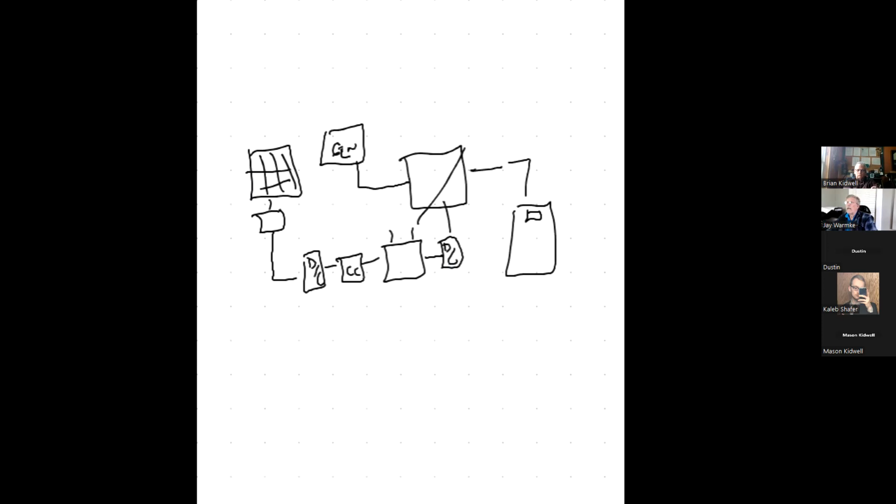So if we're coming in the olden days with one of these systems, I had to have a 48-volt array, a 48-volt charge controller, a 48-volt battery, and a 48-volt inverter. Okay, all of these things, and these are nominal voltages, but all of these things needed to be compatible. So then you would see that your voltage drop would be significantly impacted because I'm leaving here at nominal 48, maybe going a great long distance.